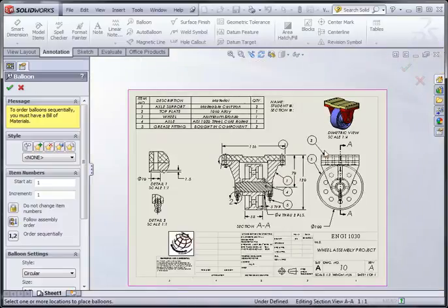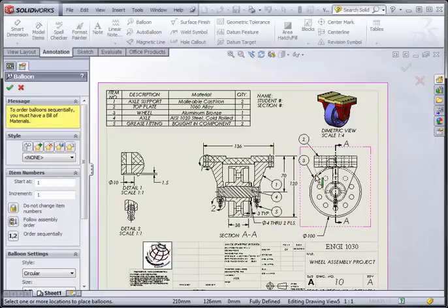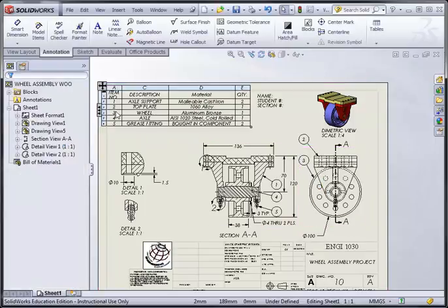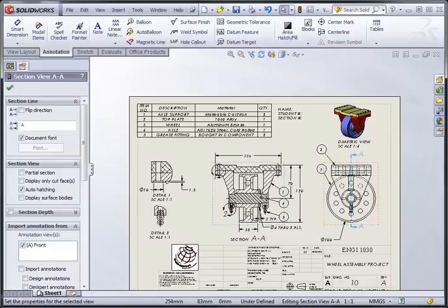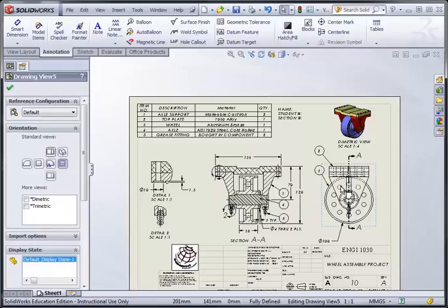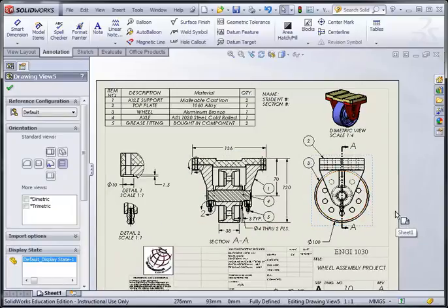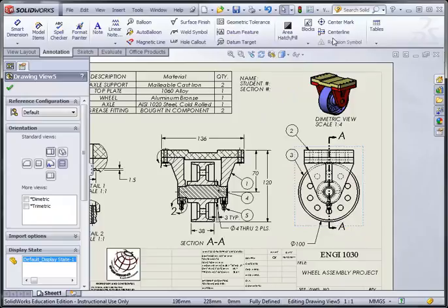Once you did your ballooning and all the parts are done from 1 to 5, you can check out of that window. So we've done our BOM, we've done our parts. You can arrange them out and see you've covered everything. If there's anything missing, like any text or any details, you can add that in. Also, for the last part, you can also use center lines and center marks.